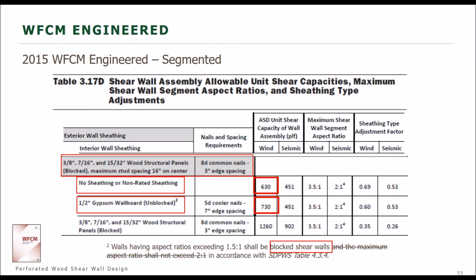It's simply a tracing paper that the user can then draw their shear walls and their openings to match or overlay the CAD drawing. That's the extent right now of the interaction between the CAD and the software. So it doesn't read to the level of where openings are and automatically apply them in the WoodWorks software.